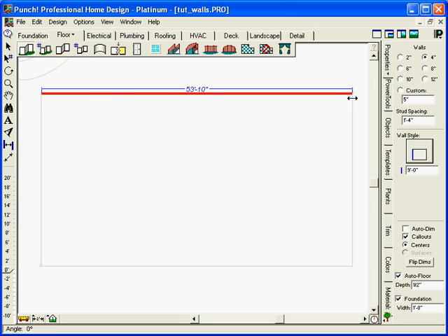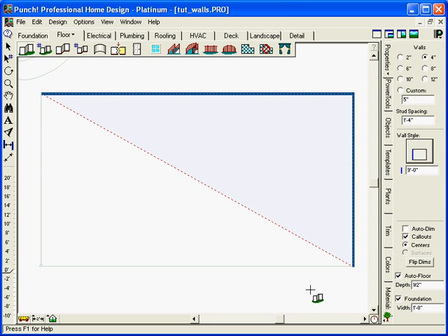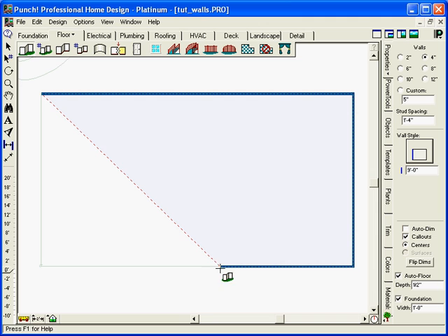Click and drag from our first point, watching the dimensions. When it says 54 feet, release to place. Click again, drag down as the dimension says 30 feet, release, and continue this process. Draw 23 feet to the left, or approximately 6 feet up, 15 feet to the left.